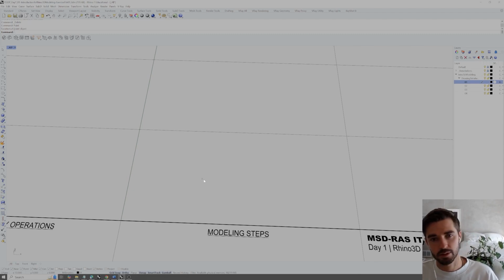So I'm going to just click to deposit a point in space. And we're going to say that we want each of these edges to be 10 units in length. So in this first step, I'm going to take that point and copy it with the gumball or use the move command. So type move, hit enter, click on that point in space, type 10, enter. So we've now moved that point, but we've now lost the original.